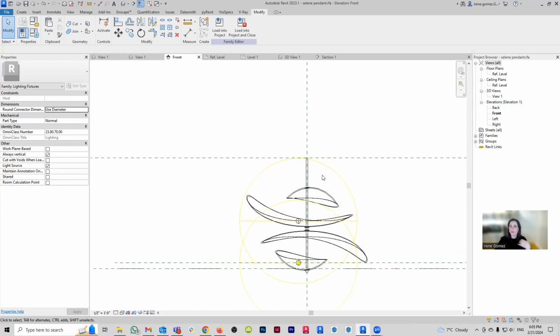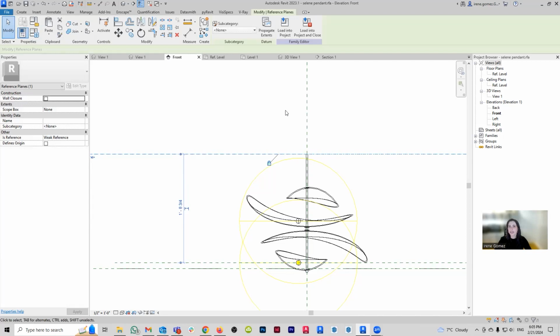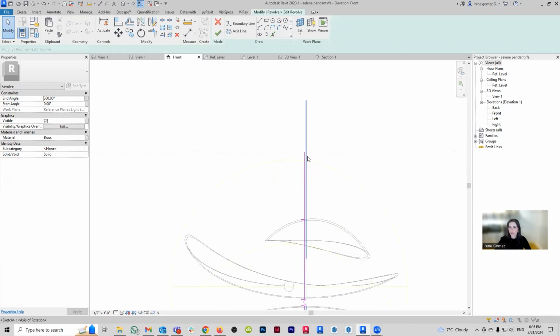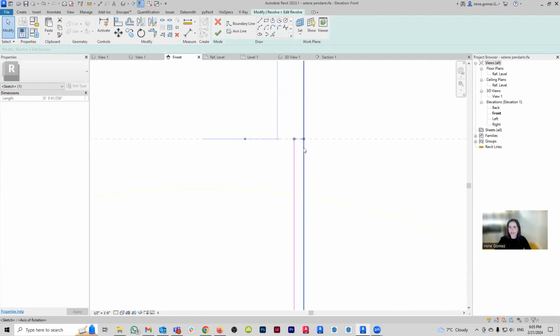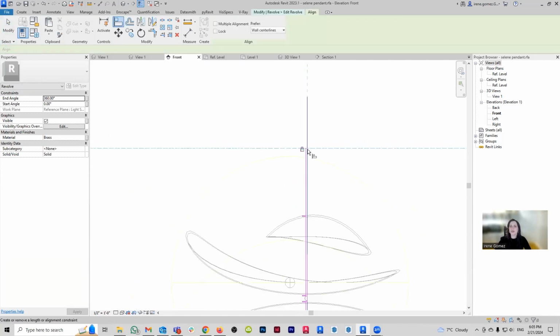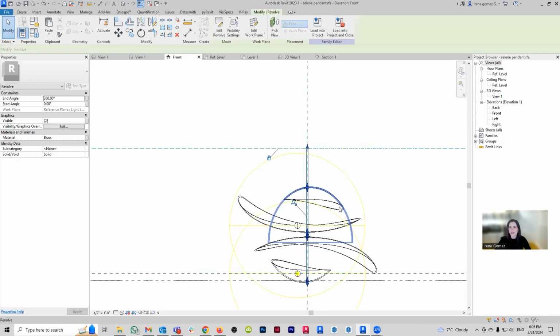But before I do that, the most important thing is that I don't actually want to move the pipe. If I want to be really precise and make sure it doesn't break, I'm going to select the pipe and go to edit revolve, and make sure that I'm locking the profile itself. Let's see if that helps. If not, there are other things we can do. Do not worry your little head. There's always another option. So I'm going to say yes.